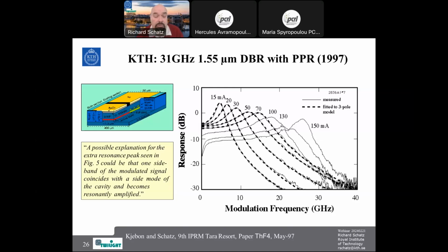You mean the photon-photon resonance and so on. In EMLs, it's not so interesting. It's possible to have, instead of an external modulated laser, which is what EML stands for, a modulator in the cavity. Then you can utilize this effect, so that instead of modulating the carrier density, you modulate the electroabsorption or phase of your EML, and that you can do very fast.